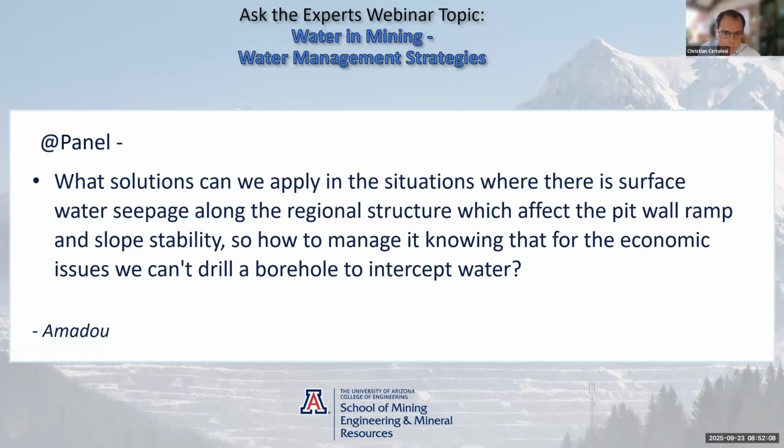That's always the best approach. And then complement by targeting the structure with pumping bores, using RC drilling and pilot holes, basically to optimize costs. That's also another good way to tackle that. Narrow holes. If you get flow, then you ream it and increase the diameter and put it as a pumping well. If not, then obviously keep it as just a standpipe for monitoring.